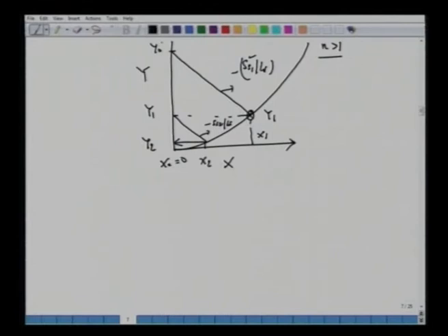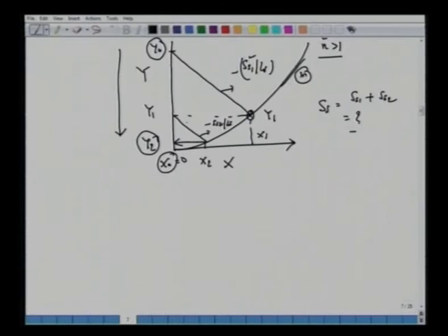X2. So I can go back to the previous question we had. Y0 is fixed, Y2 is fixed. We have been asked to reduce these concentrations. X0 is fixed here. Alright. So these three quantities are known here. n is known, slope of the curve m is also known to us. We want to know the total amount of solids. SS equals SS1 plus SS2 equals what? Alright, so that's what we said, that this Y1 is an intermediate quantity.